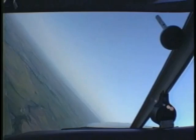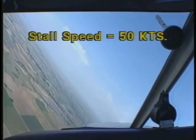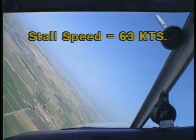It's also important to monitor your airspeed throughout the maneuver, and remember that stall speed increases as bank angle increases. For example, if the stall speed is 50 knots with 0 degrees of bank, it increases to 63 knots at 50 degrees of bank.